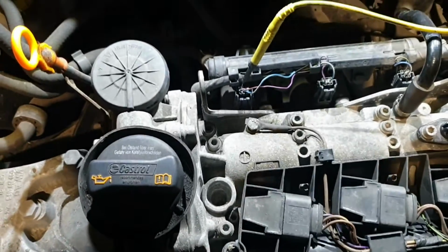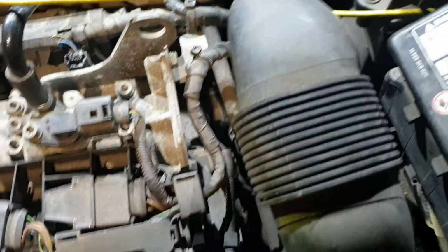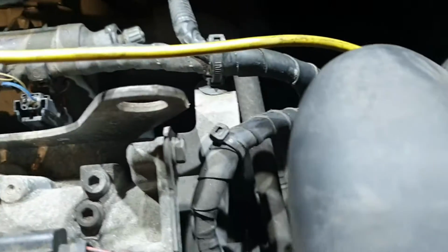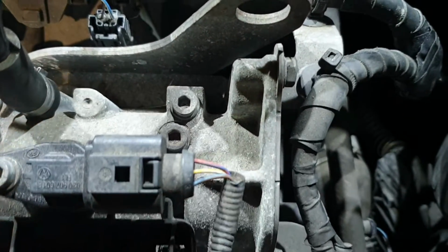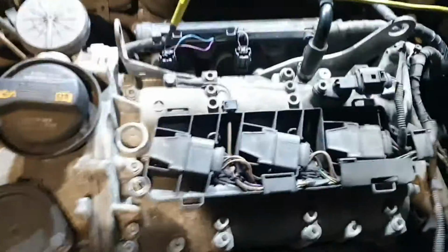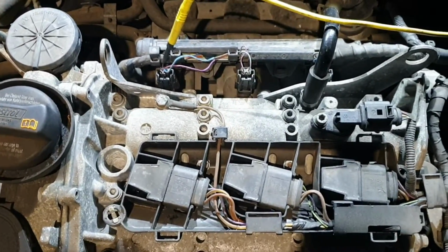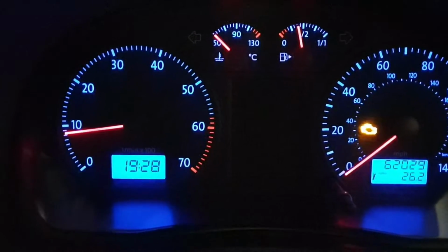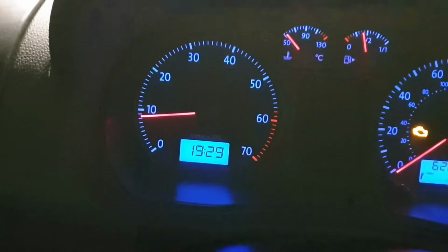So now I'm going to check the scanner, that if the camshaft position sensor fault is, I think when I repaired, that's going to be this wire, because the color looks like the same as I repaired. So this is good. Now I'm going to connect the scanner and see the fault code. Erase the fault code again and see if any fault code is returned back. The engine management light is still on, and the rev counter is very solid, staying at 850.